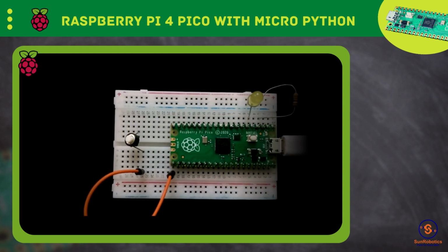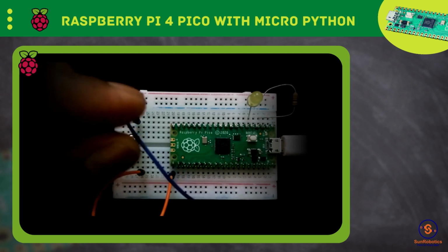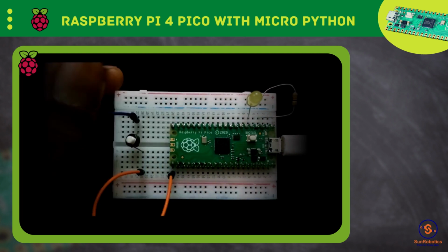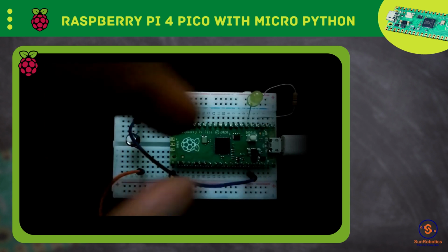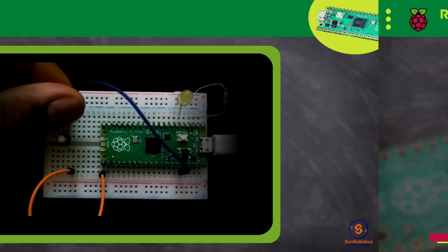Now I need one more connection. I'm taking another wire and I want to connect it to the 3V3. So 3V3 is on the side, when you're counting it is at the 5th position, that is pin number 36. I just connected it over here. Now the circuit is completed.